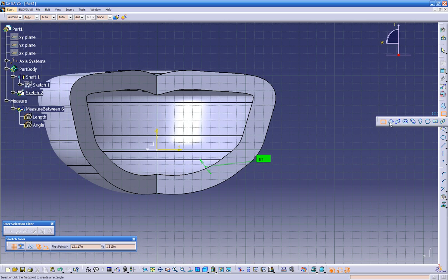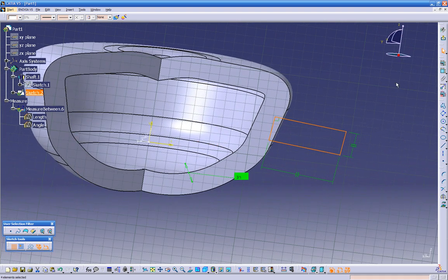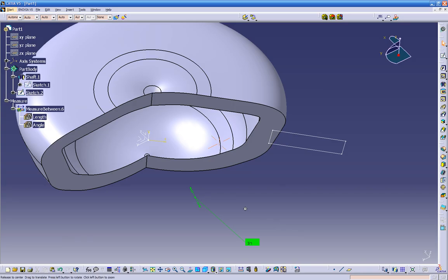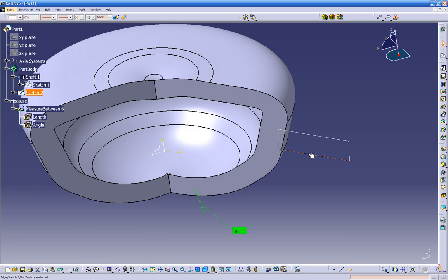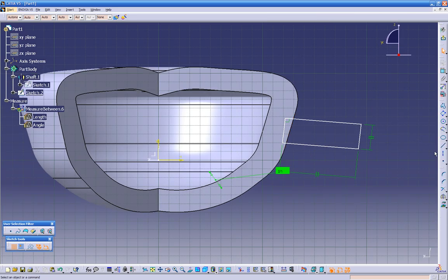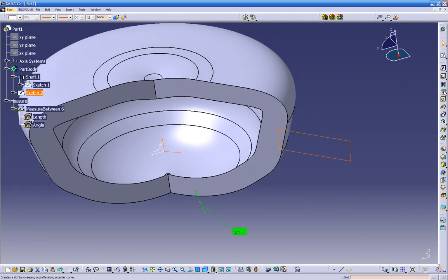and let's create a groove in here. So we got a groove. We get out of the sketch. Oh, in order to use the groove option, we have to make sure we have an axis. So let's go back on the sketch, double click on the geometry, and let's create an axis. So we have our axis over here. Okay, get out of the sketch, and now if you click on the groove,